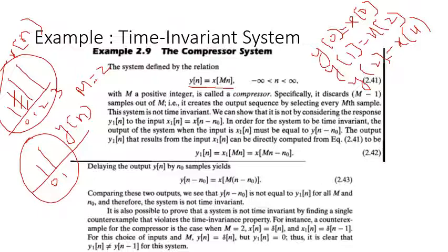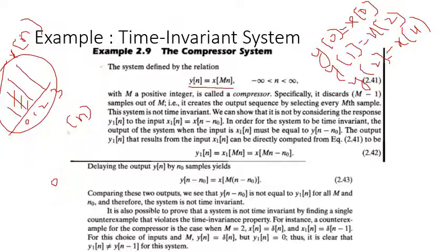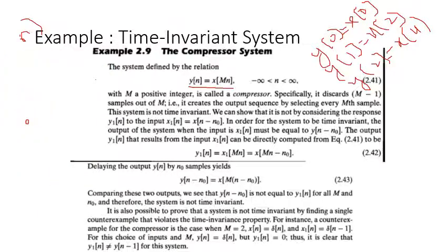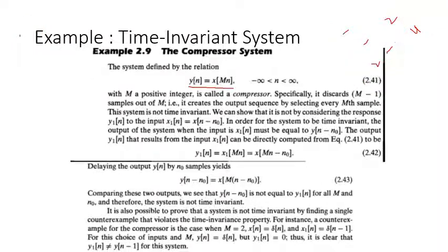So it's just like time scaling. If you multiply n with any number that is positive and greater than 1, we are going to compress the signal. And if that number is less than 1, we are going to expand the signal. You might have studied that in signals and systems as well, so I was just recapping it. So it's just like scaling, and we call it time scaling.